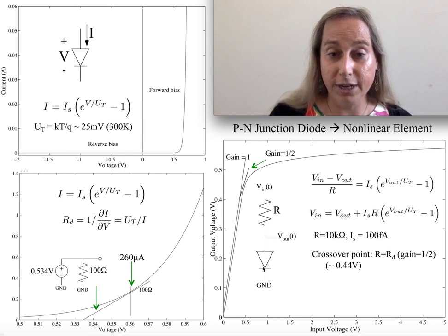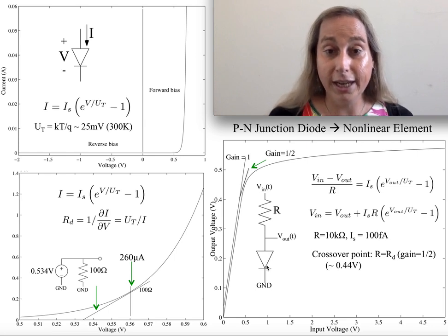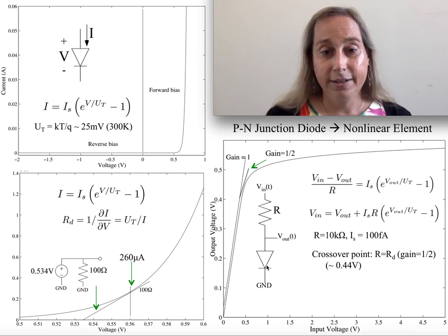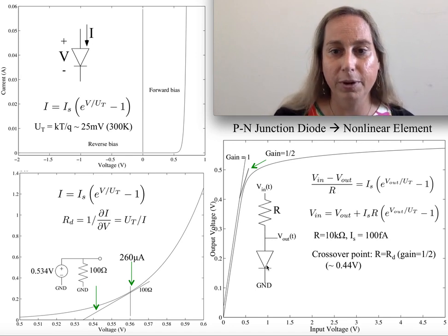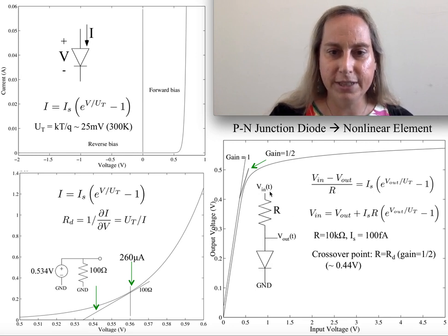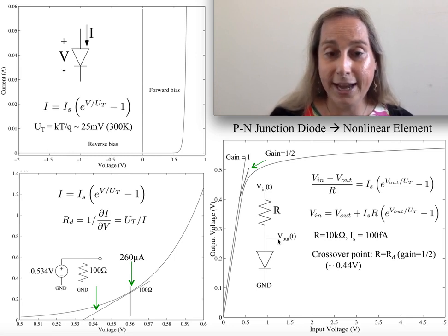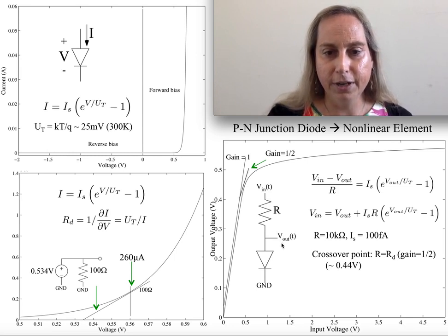One of the things you might use a diode for is actually getting light. If you've ever seen a light emitting diode, or an LED, that would be a diode made of various materials that give you various light properties coming out, or maybe optical filters to help with that as well. You're going to see structures like this, and you might imagine, what happens if I take this input and sweep it and look at the output voltage? Well, some interesting things happen. When the input voltage is very low, the output voltage will be fairly low, and I won't get a lot of current through this diode.